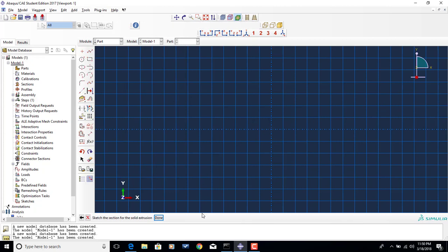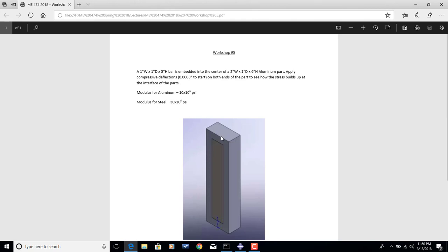You'll see here comes our grid, and first of all, we should bring up that we can do this with 3 different symmetry planes. We could cut the problem in half coming up and down, we can cut it top to bottom, and then we can also slice it in the depth as well.